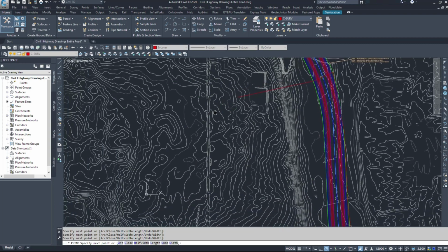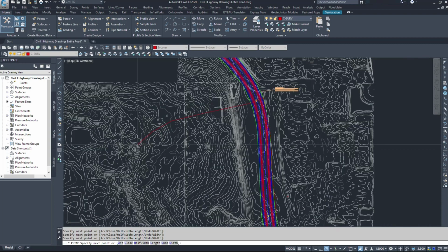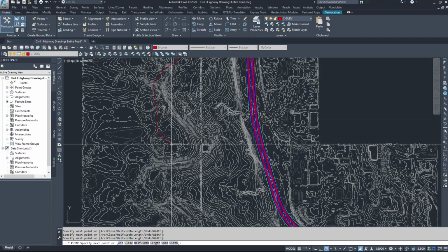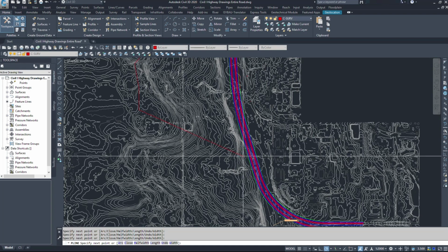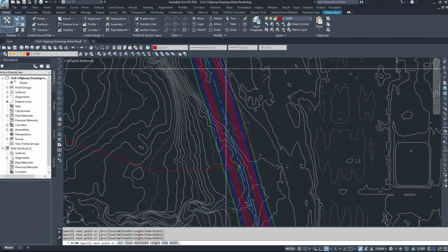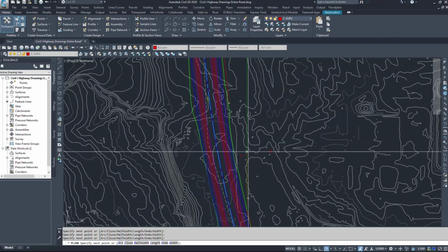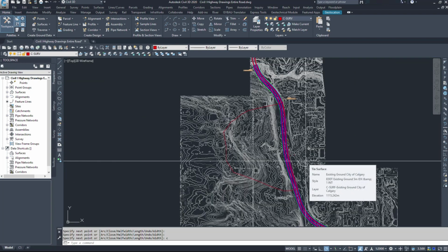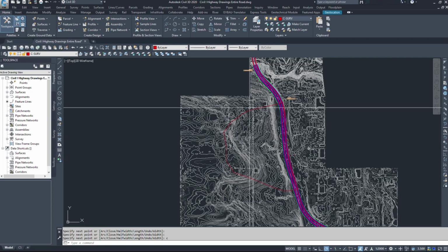I'm going to draw a polyline here, roughly, trying to figure out where this water will flow down to the road, is basically what I'm doing. I'm going to cut it off around the high point here. Station 2000 is down here, so if I follow that, the water goes through here, more or less. Station 2000. Now, obviously, you would do this to a higher degree of accuracy, but for the example of this exercise, I'm just going to do it this way.